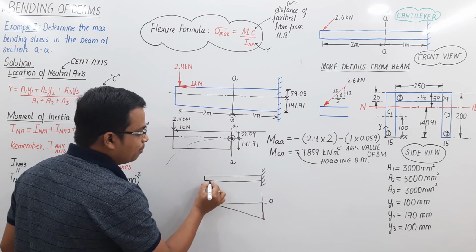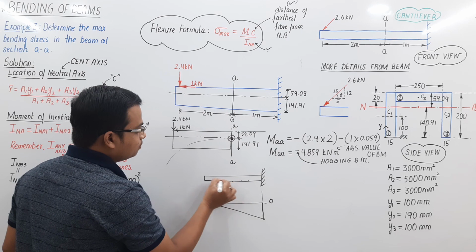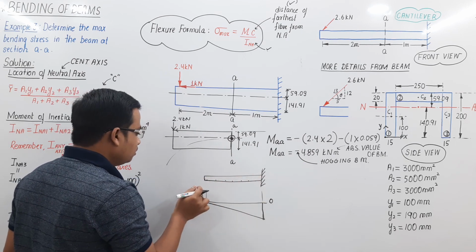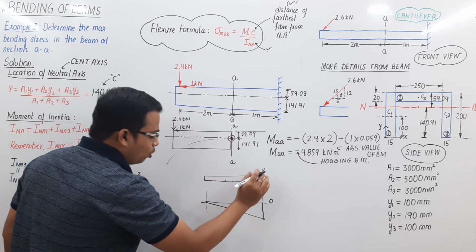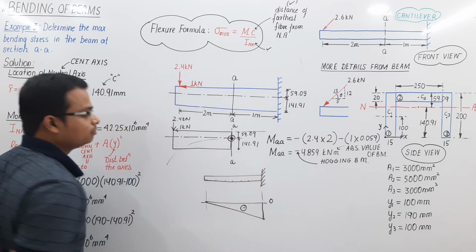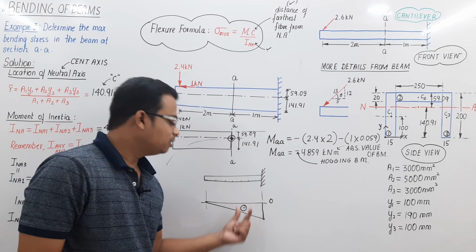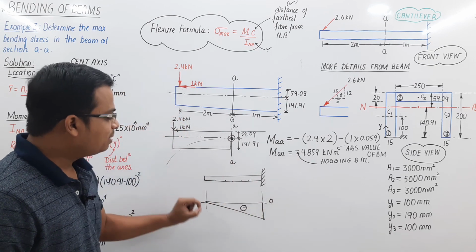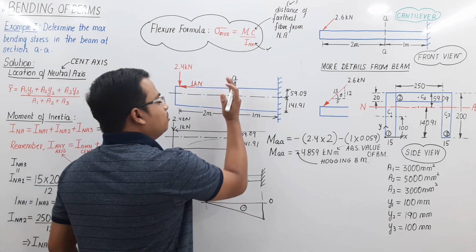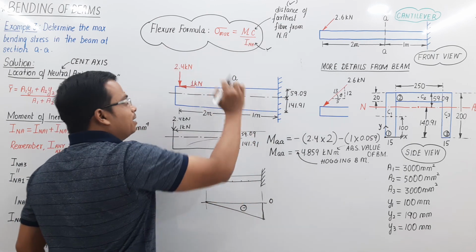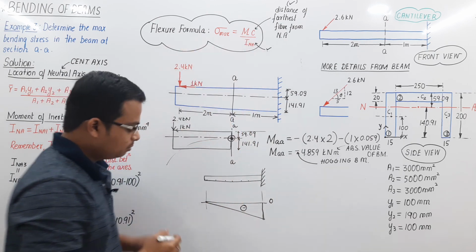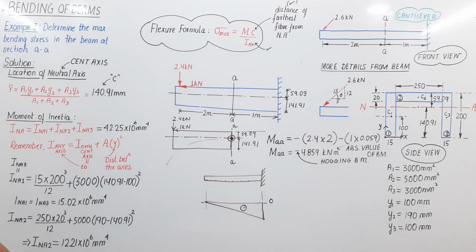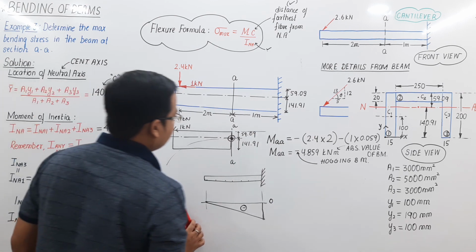Once you start from the fixed end and move towards the free end, all the values are going to be negative. So don't worry, this is exactly the reason why you've got this negative sign over here. What we are basically interested in is the magnitude of bending moment at this cross section, which we are going to plug in over here to find the maximum bending stress, and everything will be over then.